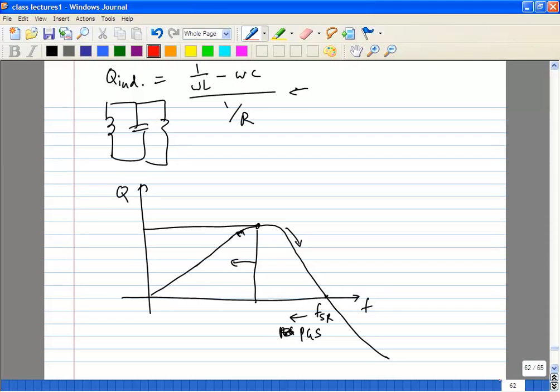Okay, and at that point of time, you need to make a decision on whether you want to match the impedances or whether you want to work with lumped elements. For example, I think we discussed this in the first class, inside the chip, you try not to match. Let's say if you have an LNA, you want to drive a different circuit. You don't necessarily have to match the output to 50 ohms. Outside the chip, you want to match to 50 ohms because you have come to the domain where microwave effects are very predominant. Inside the chip, your distances are much shorter.